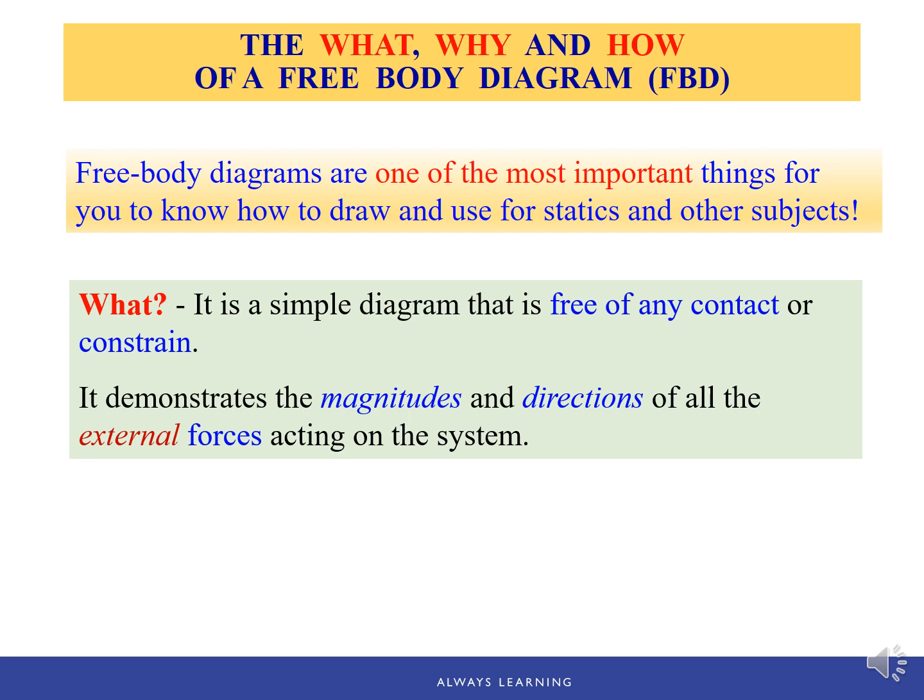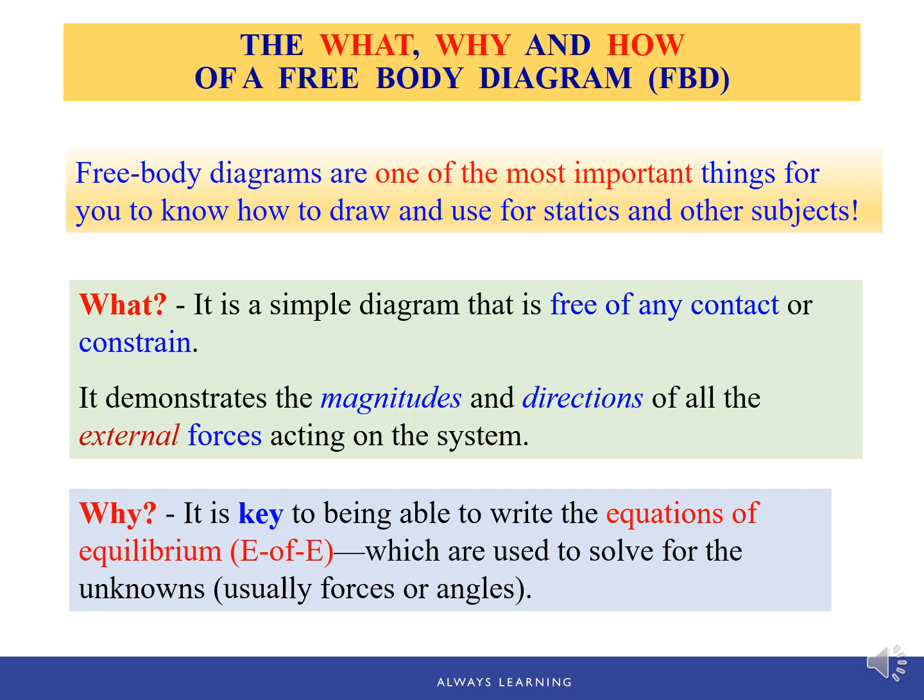A free body diagram, first of all, is a drawing that shows all the external forces acting on the particle or on the body. And why is it called free? Because the particle is isolated and free from its surroundings. And why do we use a free body diagram? Because it is the key to being able to write the equations of equilibrium, which are used to solve for the unknowns.